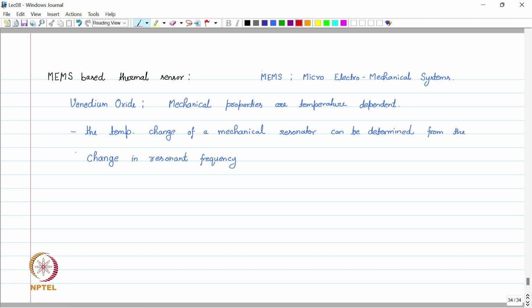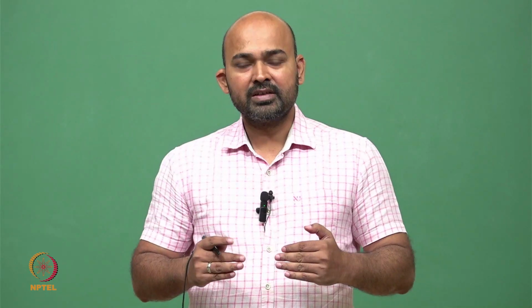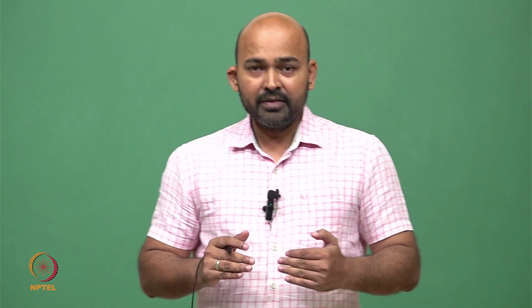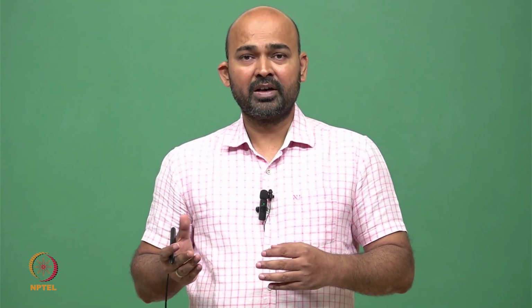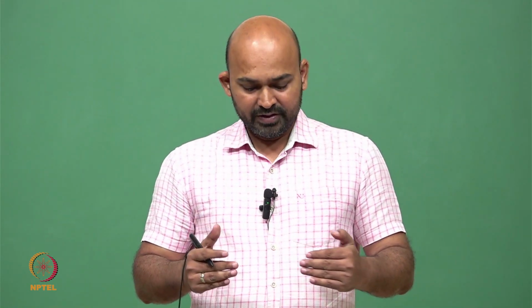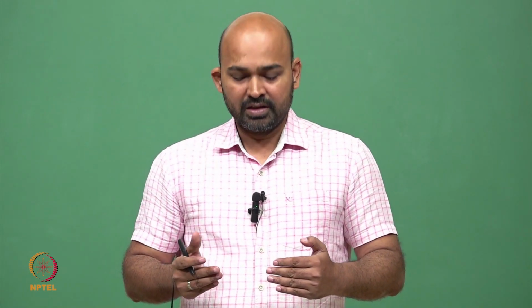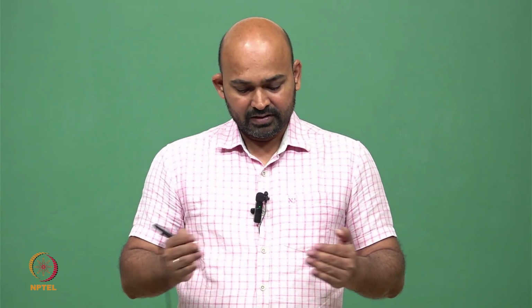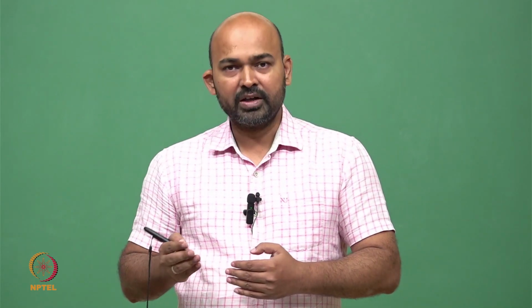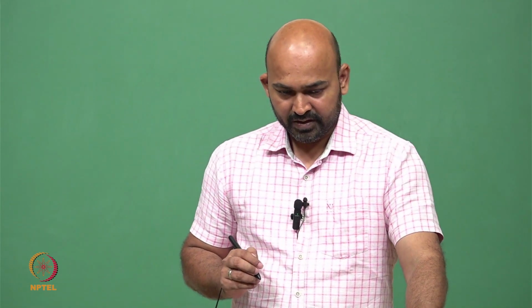So we have a MEMS device which is resonating at a particular frequency, and if the temperature is changing, then there is a corresponding increase or decrease in the quality factor, and because of that we get a change in the resonant frequency. This change in the resonant frequency with temperature we can detect, and this gives us the corresponding output in terms of temperature.